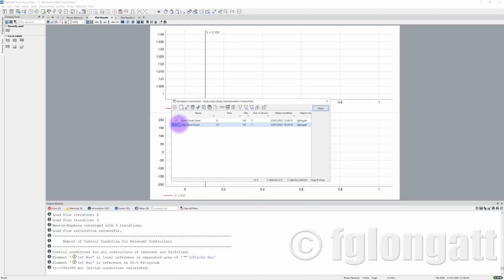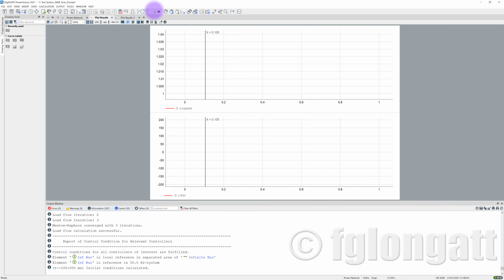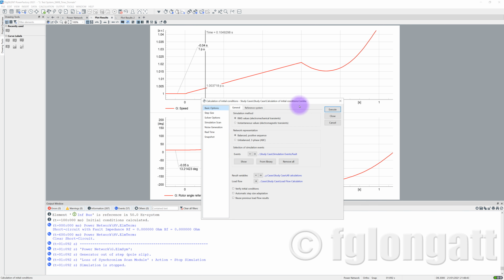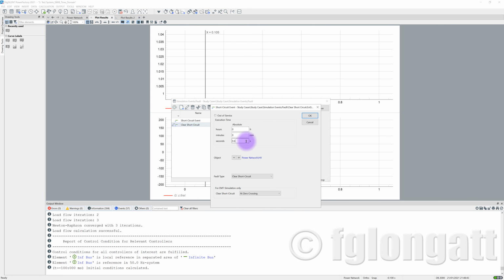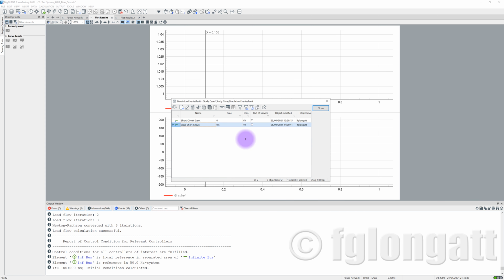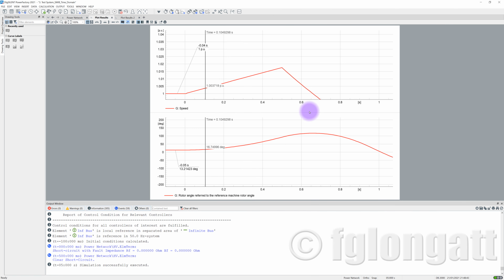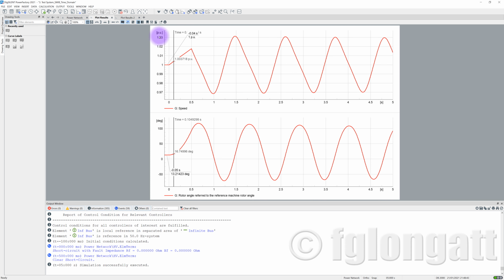Now, let me clear the fault at 600 milliseconds. I am reducing the time, okay? Right now we are at 600 milliseconds. The system stays unstable. Let's go for 500 milliseconds, okay? I run my simulation right now and, oh! The system is stable at 500. Look over here, the simulation did not stop. In this condition, the system is stable.